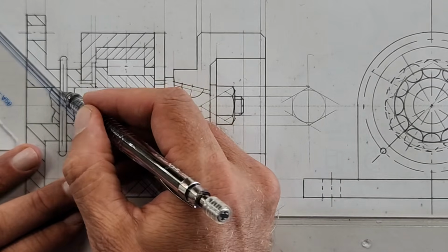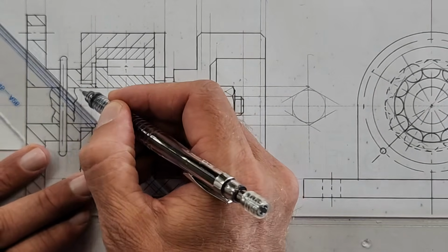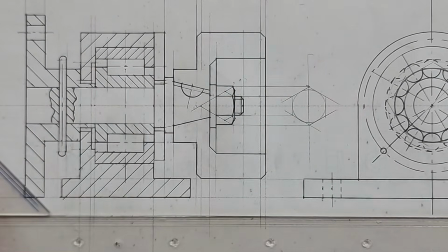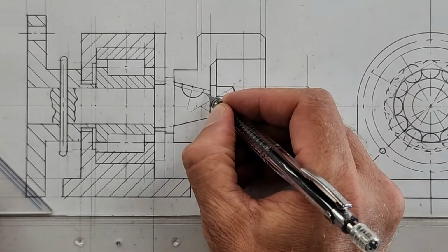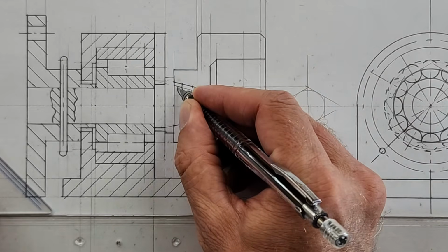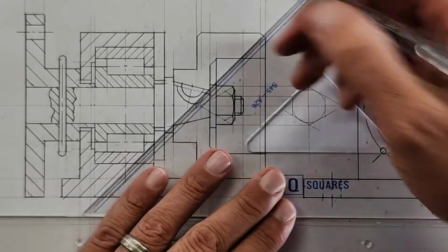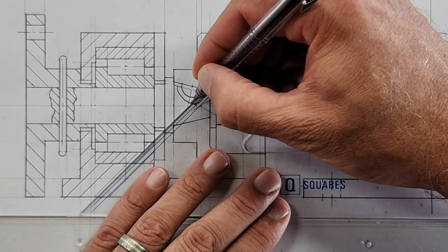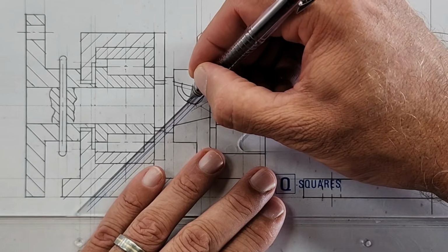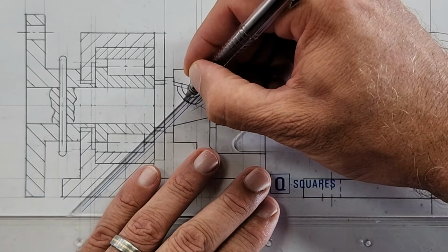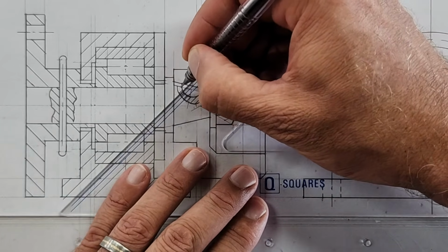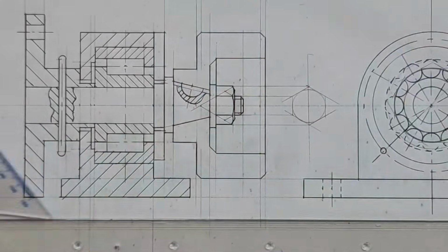Okay, the actual fastener, we don't section or hatch. Okay. The other part, there's a key way, again freehand, flip it, and again the smaller the component, the closer our hatching can be. Can actually have used a different pencil here, made it easier.